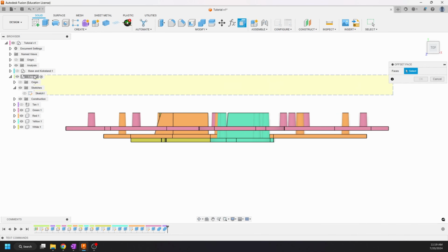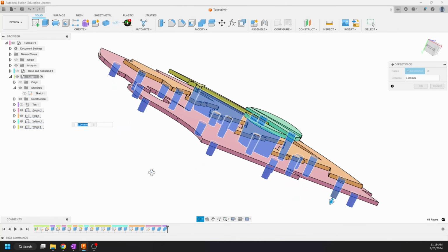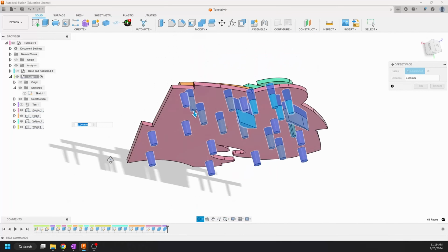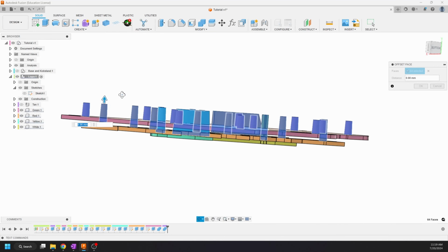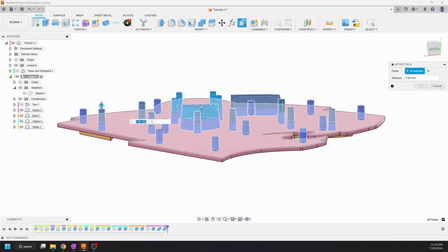And since we have the logo, the overarching component that's housing all of these other components, it will allow us to select anything within that component. So right to left selection will select all of those pins. It does not select the bodies, the attaching bodies, just the pins themselves. So this is exactly what we want. This is where you kind of hope and pray that it's all going to work together.